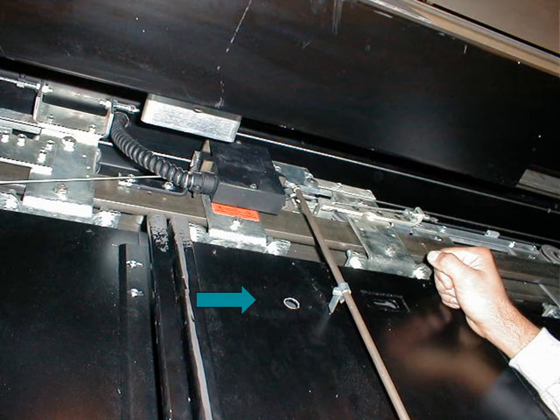In this slide, we are standing on top of the elevator car in the hoistway and are looking at the back side of the hoistway door. The hole in the hoistway door allows us to insert the drop key through the door and actuate the interlock device. The interlock device keeps the hoistway door closed and locked when the elevator car is out of the landing zone.